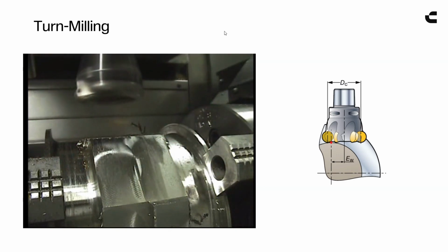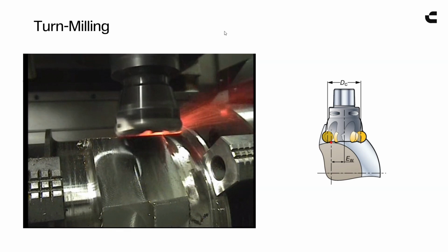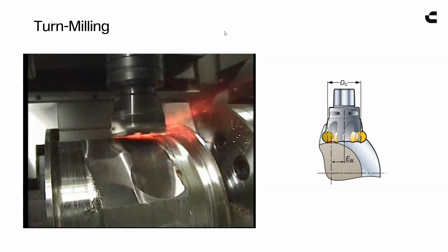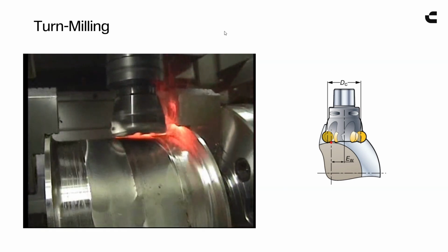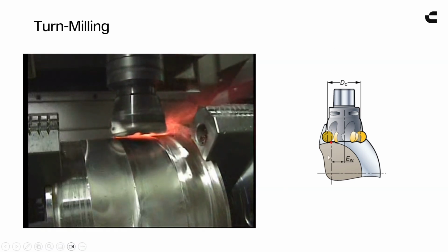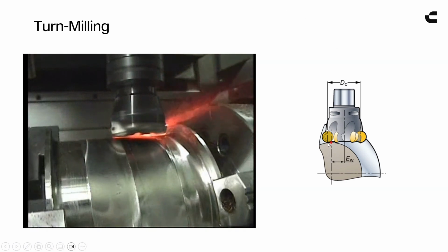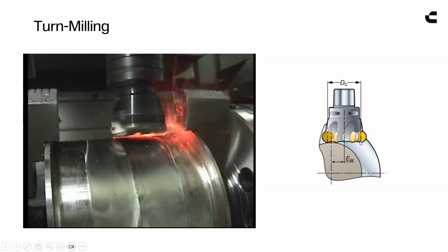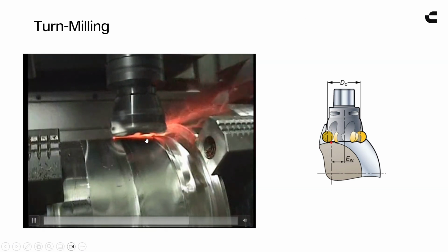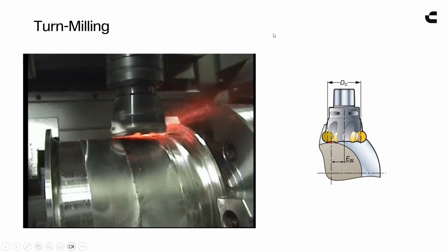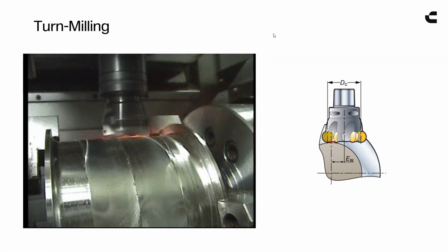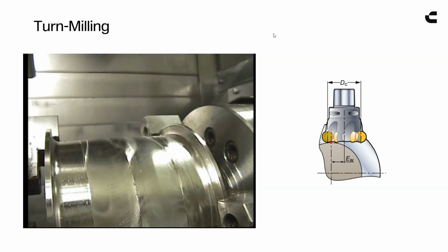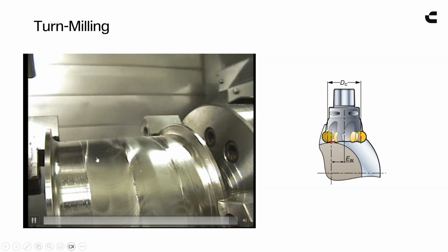So there's a large boss pad in the way that you can't turn this middle section. So what you have to do is actually position it so that the cutter is cutting on its leading edge off Y0. In this example, if we were looking at a side view of the cutter, it'd be cutting here on this front leading edge where the red dot is, and then the back end of the cutter is hanging off the part. So that's what we're trying to show here on this image. But it's a fantastic solution for milling a lot of material really quickly and even getting an excellent surface finish. So in this example, you're just seeing a ceramic mill and it's just doing a main roughing.